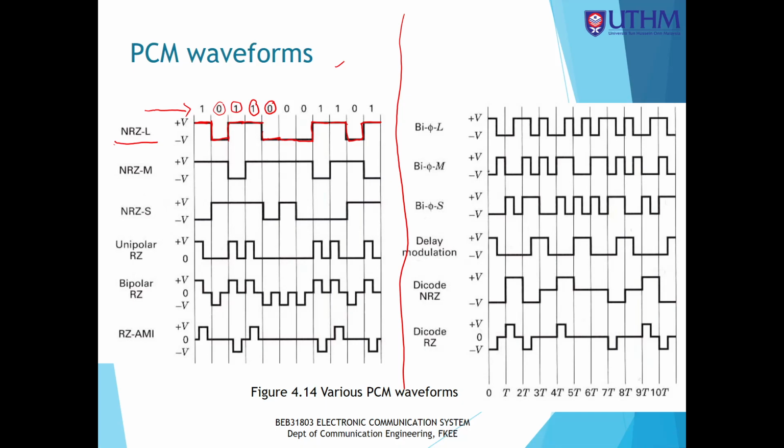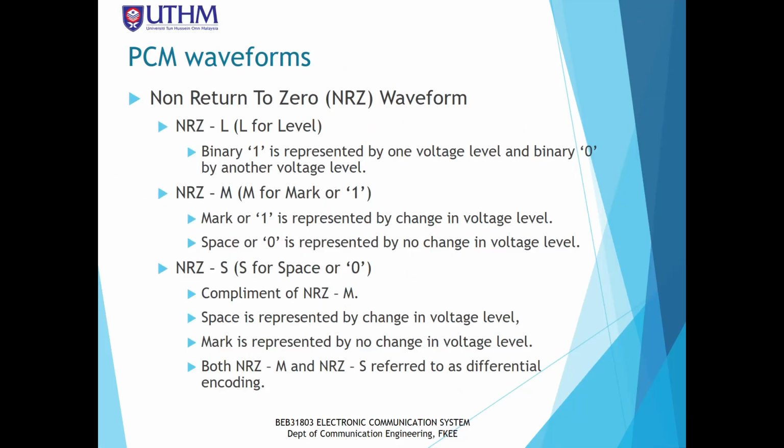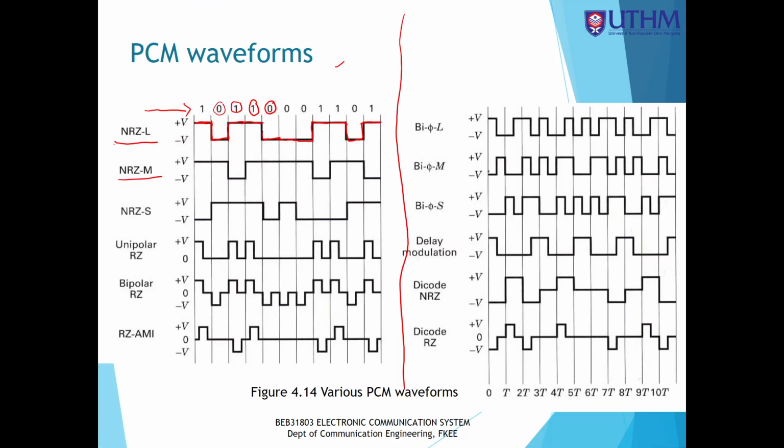What about NRZ-M? M is for mark. NRZ-M changes whenever there is an input logic 1. So whenever there is an input logic 1, the output polarity will change.